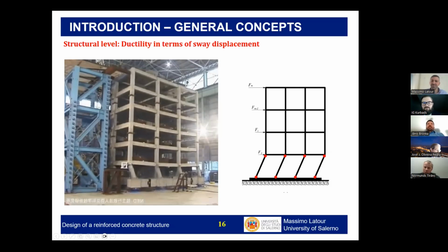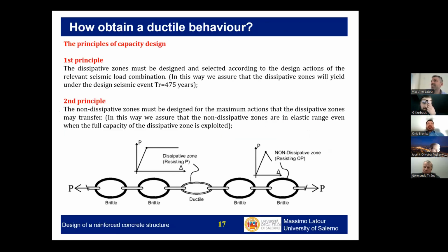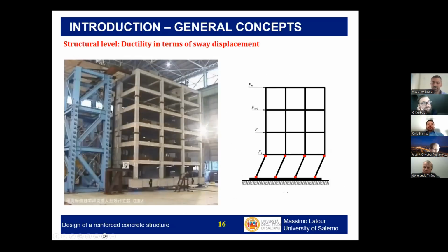Maybe it's another slide. Yeah, and there's like a follow-up with a few questions. Would weakening of the beams and their joints improve the situation? And also in that particular situation, should joints have been designed more ductile? Poor hierarchy design, yes, for sure. This is a test done in Japan, but it is done on a structure which is not seismically designed.